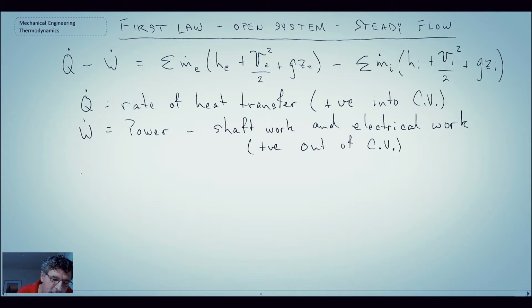And we also have, you'll notice, enthalpy leaving and enthalpy entering. Sometimes, depending upon the way that our fluid streams work, we can pull out the mass flow rates, and then we have the change in enthalpy of a stream being h exit minus h in, so that would be the enthalpy change.